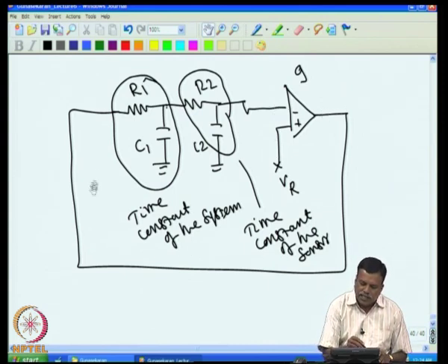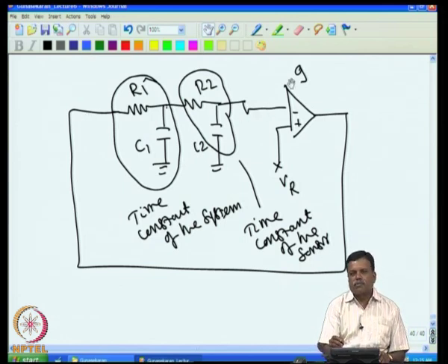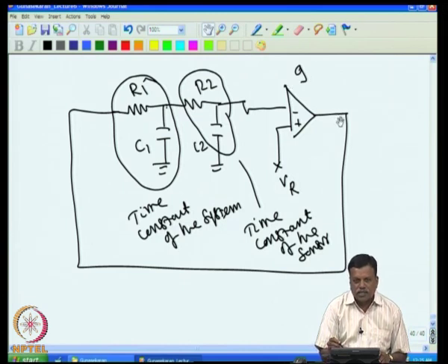Now, if I have a system like this, naturally it will oscillate, because if I increase this, the increase takes place with a time delay, and the temperature in the oven is sensed only after again some time delay given by the sensor. Because of that, by the time it reaches the actual temperature, the voltage here has already gone much higher, and the net result is the system will keep oscillating many times. Now, if the gain is sufficiently large here it will oscillate; of course, if the gain is less, it will not oscillate.